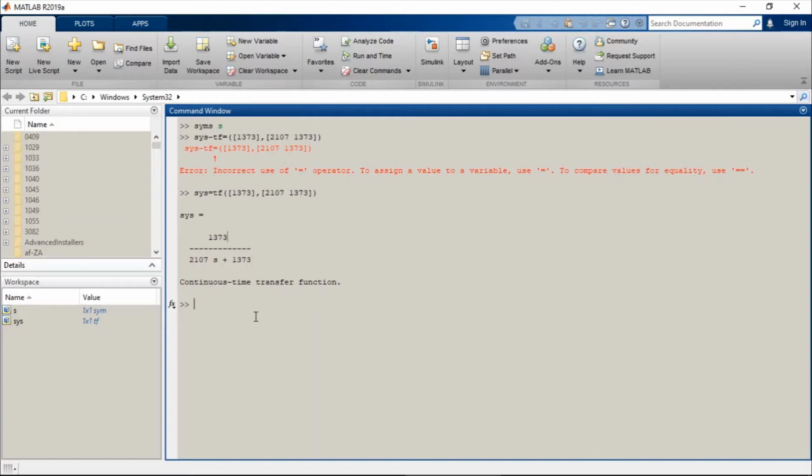And I think my biggest issue with that was I couldn't find any kind of dampening force. That's just because I don't know exactly what would dampen the car accelerating other than air drag, and maybe if it's on a hill, some kind of incline, or something along those lines, and then whatever isn't already affected by the weight of the vehicle. So I just left that alone, left it as first order, and decided that I would model it based on that.